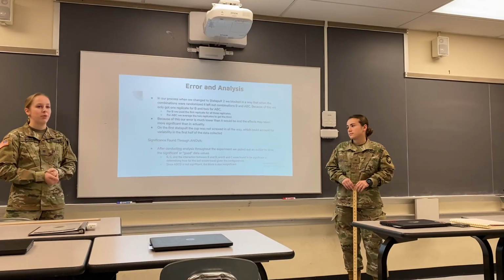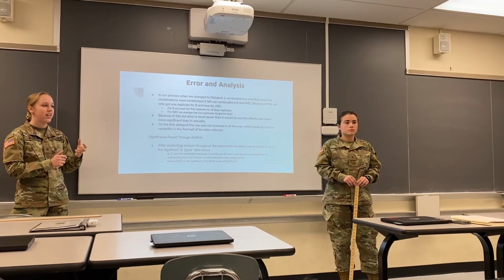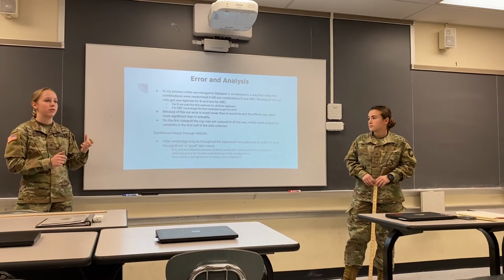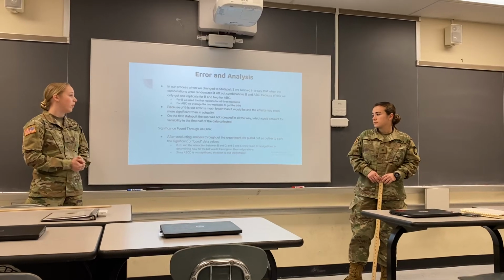Also, on our first Statapult, what could account for some of the variability is that our cup wasn't screwed all the way in, which we should have checked before. That could account for some of our error and maybe the reason why our data wasn't normal like we expected.